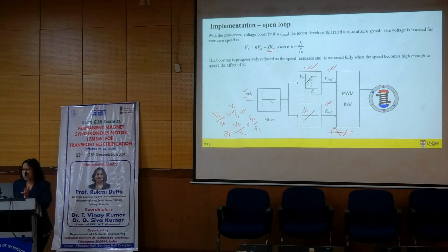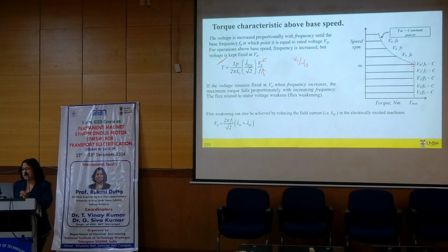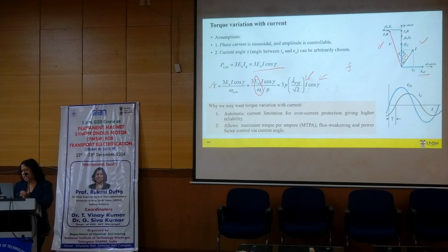Okay, and this current control is in fact used in the BLDC motor very much. The simple BLDC motor, how do they do torque and speed control? They simply control current I and gamma with some simple methods. Maybe they will make the current proportional to torque, have a lookup table and try to get that current, and that's how cheap motors do speed and torque control.